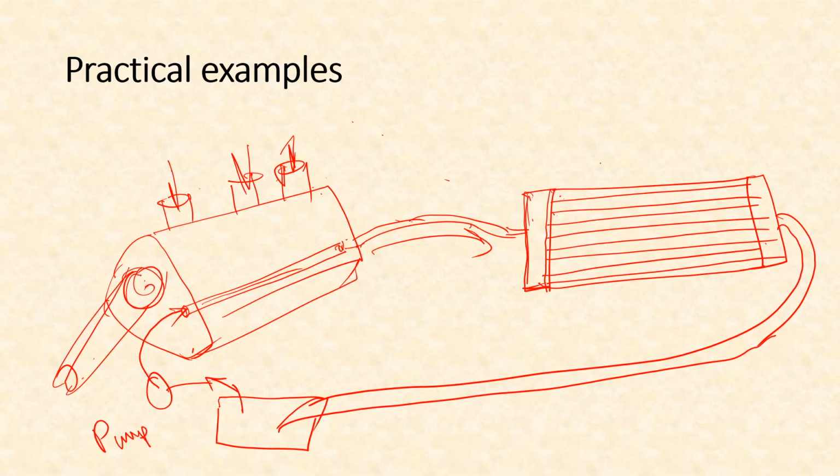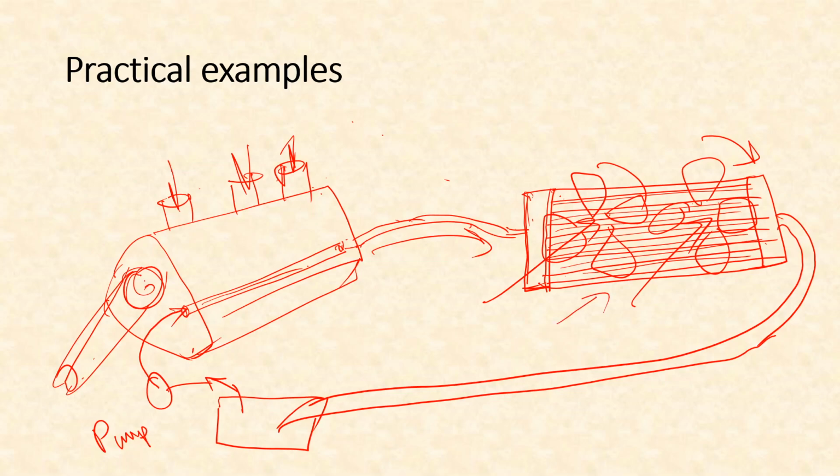Because the water is going through this hot engine block, the water will be heated up, and while flowing through these small tubes, it will be transferring all that heat to the metal walls of all those tubes, and there will be 1 or 2 fans blowing air into the radiator, and that way the heat which is radiated out of those metal tubes is also carried away into the atmosphere because of the wind velocity. So this is a very good example of pipe flow in parallel.